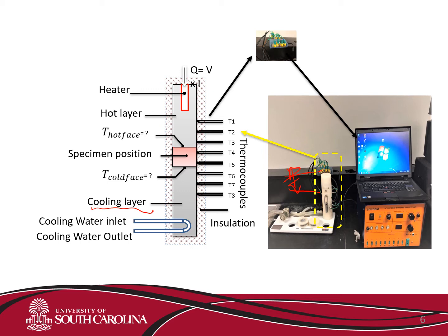Make sure the water flows into and out of the system, because if you shut off the water, the system will burn out, maybe after an hour. In this figure, this is the cooling water. The specimen is sandwiched between the hot layer and the cold layer, and this is what we are going to measure for thermal conductivity.